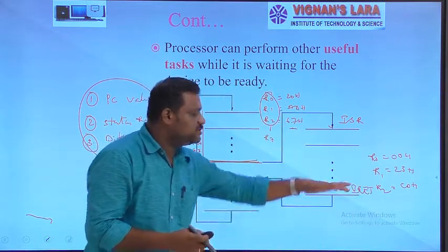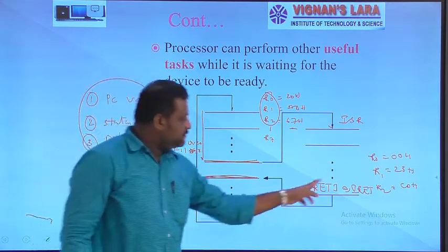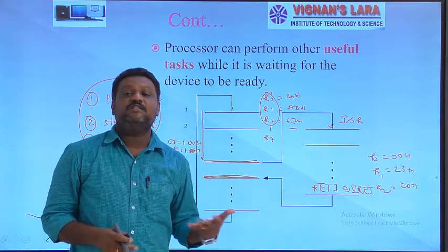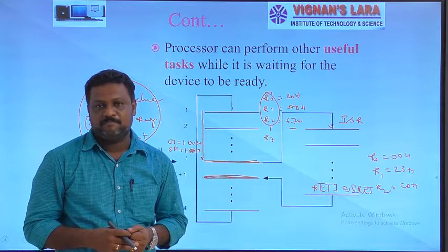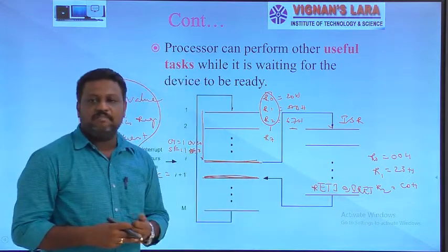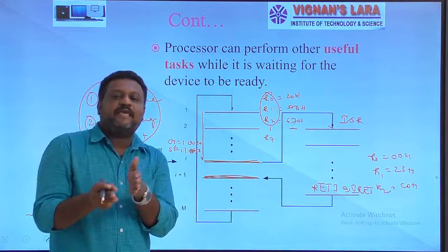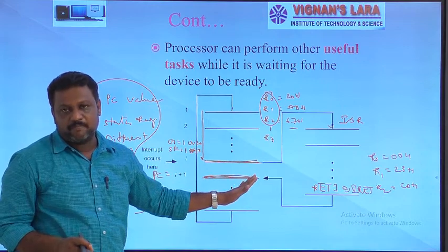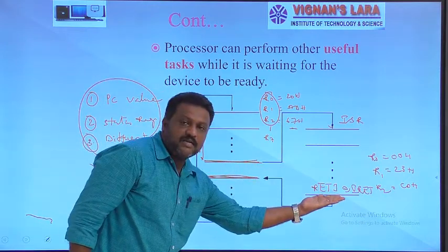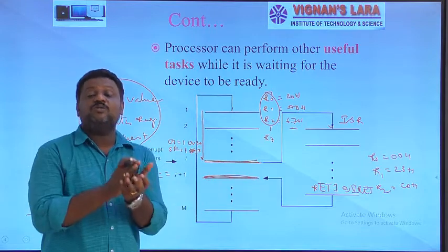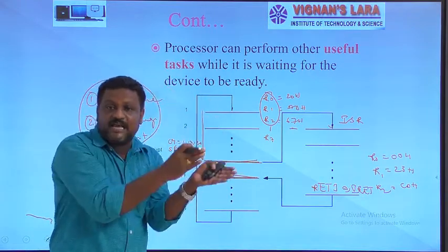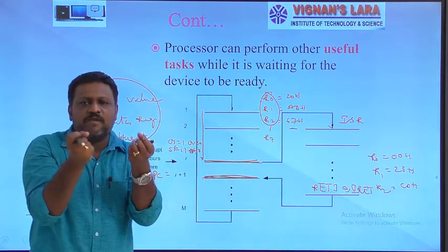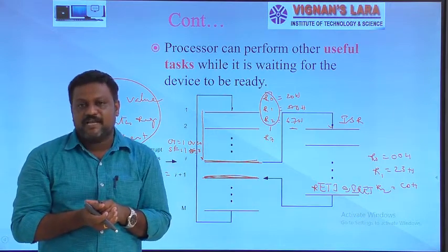In different processors they use different instructions. The meaning of both instructions is the same. RETI or IRET both indicate the same, that is termination of the interrupt service routine ISR. By execution of this particular instruction, the execution sequence again changes from the interrupt service routine back to our previously stopped program. Once you move execution from this ISR to the previously stopped program, whatever information was stored previously in the stack, before shifting execution from the current executing program to the interrupt service routine, the same information we take in reverse order from the stack.